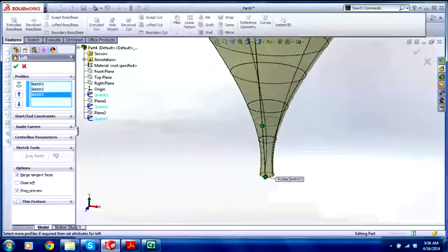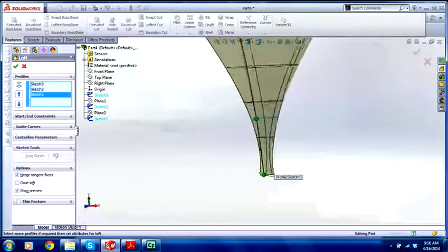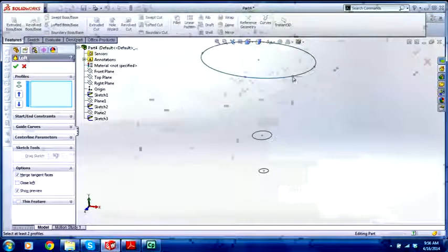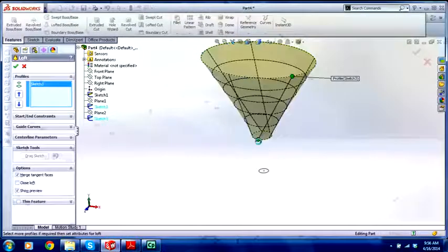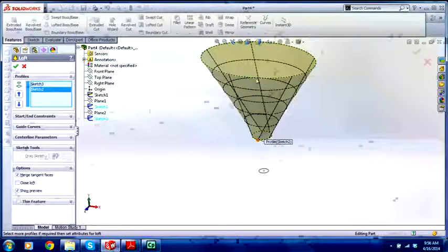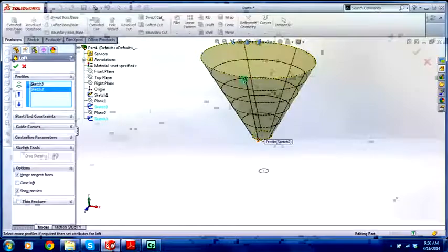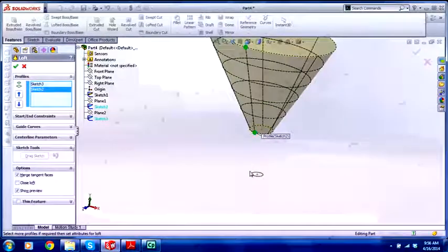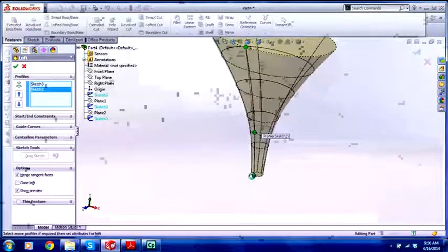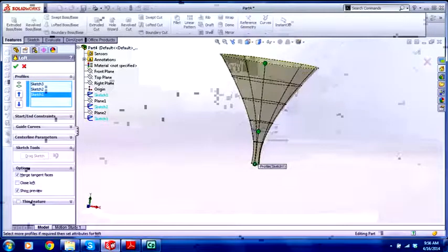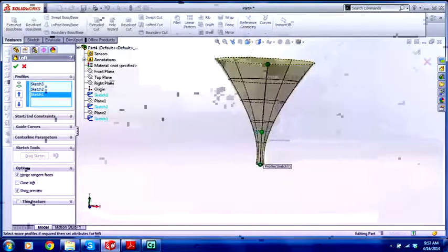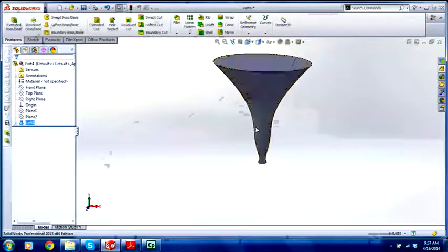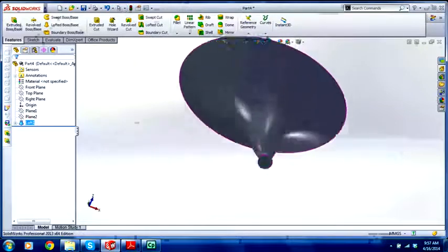Did you see what I just did there? I think where I click, I'll do it again, loft. If I click over here, and then I click there, yeah, see it picks that point, and I can move that control point to kind of manually take the twist out of it, and I go to there. Okay, so really do your best to try and not have any major twists. This is what it ends up with. I don't know if you can see that.